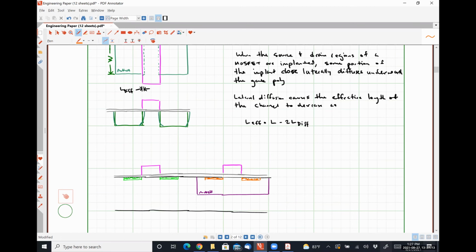So I put in a thin but extremely highly doped region. Like if my implants would be considered N plus and P plus, these would be plus plus. So they're even more heavily doped, but it's a very thin region. And then I effectively expose that same area and implant ions.